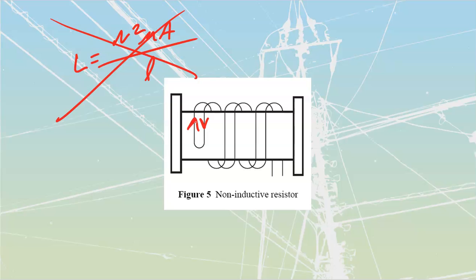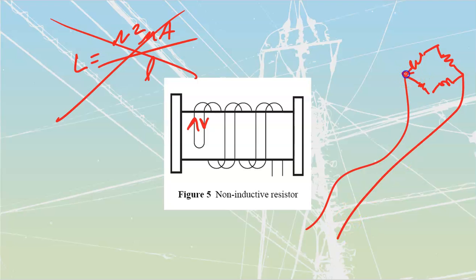Those load cells have conductors that are measured as being part of it. It's a very small amount of current that goes through what we refer to as a Wheatstone Bridge. The way that Wheatstone Bridge sets out a value of voltage, and we measure that voltage value across the center of the Wheatstone Bridge, is what tells us how far we've distorted our beams.